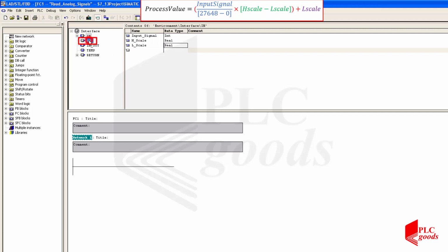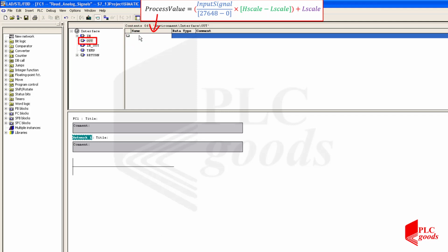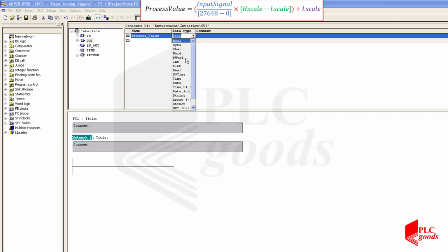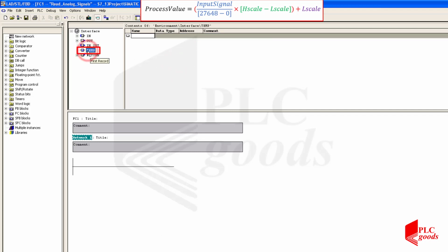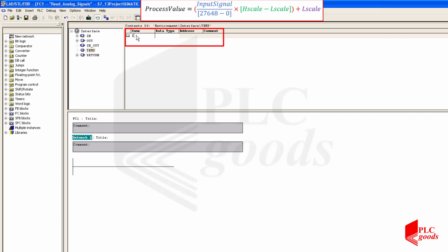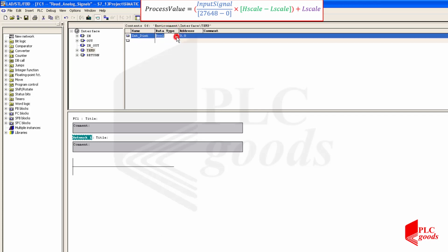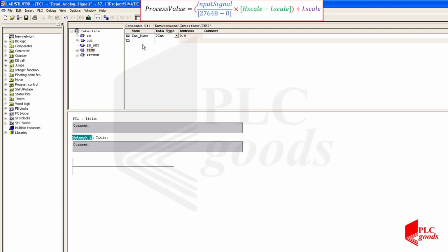Well, my function has one output, the process value, which can be the received electrical signal or an industrial parameter such as level, temperature, flow, and so on. Okay, I also need some internal variables to implement the mathematical function. First, let's define two variables. I'll use them to change the format of the received analog input from an integer number to its real format.